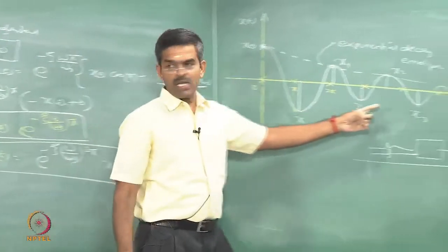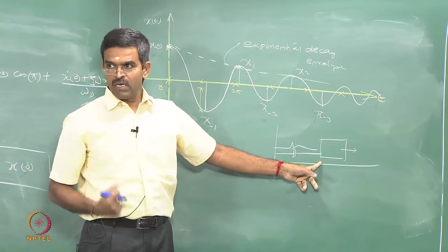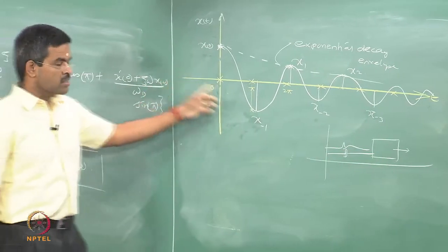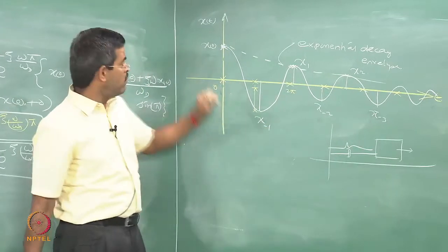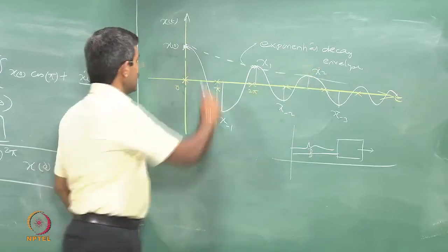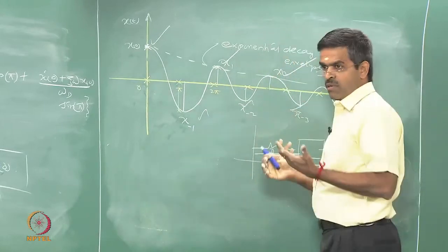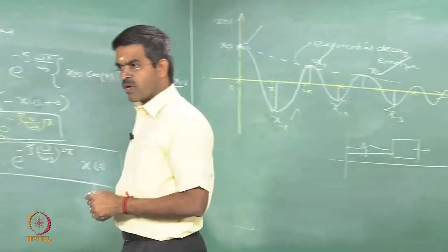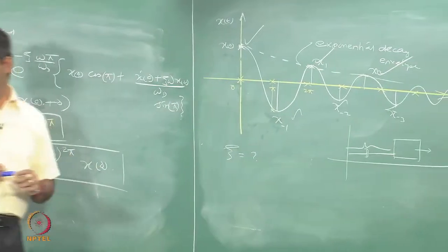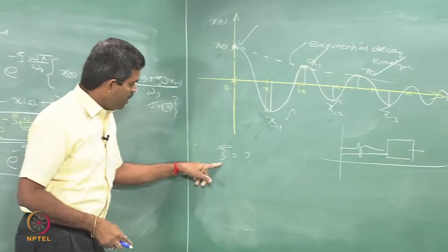And I am not plotting this from equation 7, I am plotting this from an experiment which is directly obtained from the instrumentation, maybe accelerometer, maybe transducer. So, I get this curve. From this curve I can always read these values, whatever may be the number, right. So, it means these amplitudes be positive or negative is known to me by magnitude, I know them, okay. Once knowing this, how to get zeta? That is our question, because we are interested in knowing at what zeta this decay occurred.